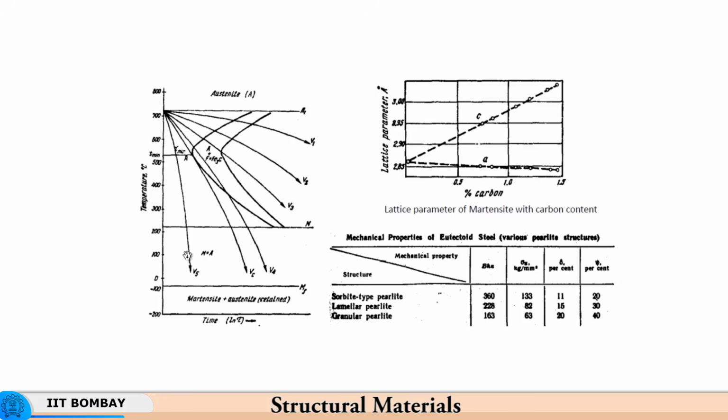Now, that is one reason why we observe on many occasions that if the cooling rate is too rapid, the part cracks. Cracks are formed because, due to volume expansion, tensile stresses get introduced, and we will see why the part cracks when we go to the subsequent slides.